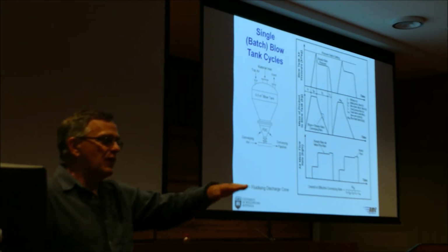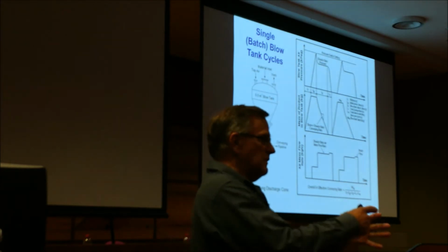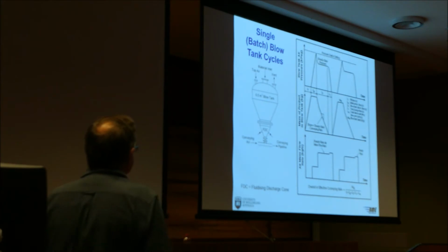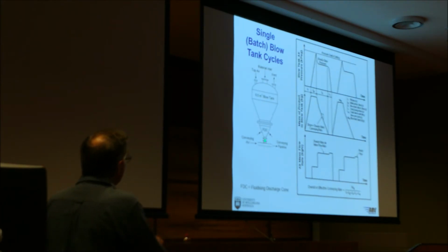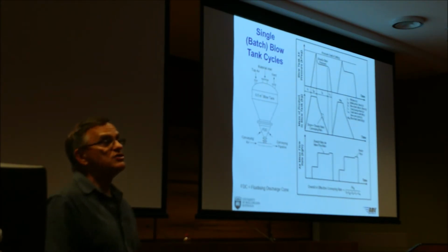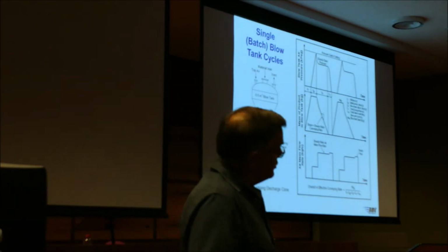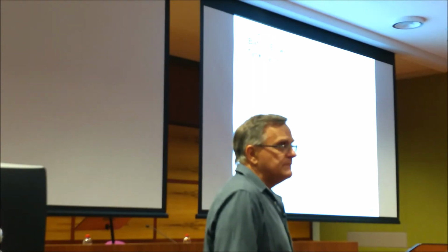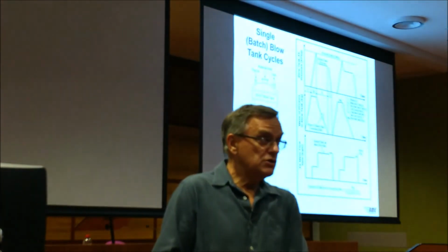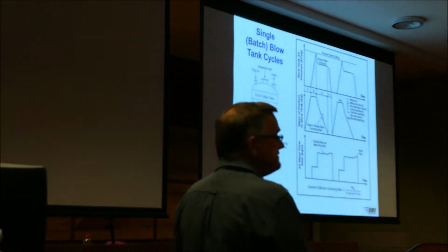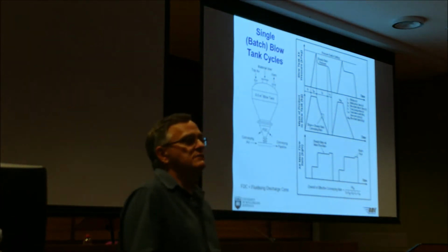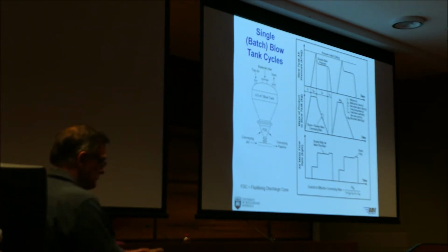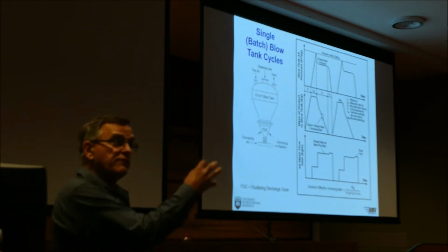Alright, you want your valve to open quickly, not a butterfly valve, but a full bore valve, open and close quickly. Because any valve that you put in there, if it's slow actuation, and if your powder's abrasive, you will rip the guts out of that valve pretty quickly. It won't last long. So you want to open quickly and shut quickly. With the air valves, it's not so critical because it's clean. But when there's powder involved, you want your valves to be full bore. There's nothing in the material flow.